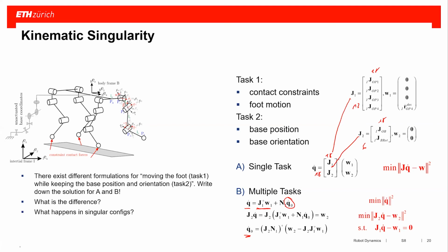So in other words, we ensure that we are consistent with the constraint, we are following the end effector, and we're just trying to somehow make sure that the base is barely moving. So what will happen there is if I hit my limit, I will still continue to follow my end effector, but I have to modify then my base.